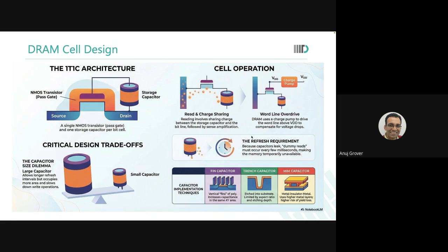If the VT is high, then it takes a higher voltage on the gate to turn the transistor on. Basically, that current and voltage curve, the VGS curve that we had in which we had the logarithmic scale, where we talked about the sub-threshold flow, that entire curve shifts to the right when the VT is high.